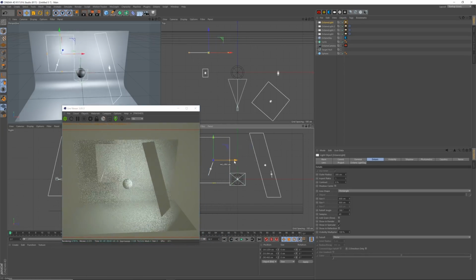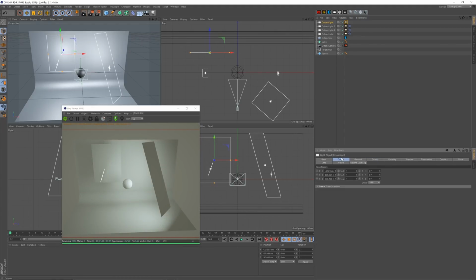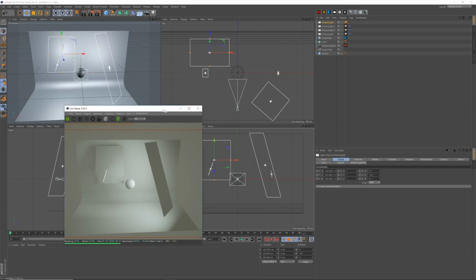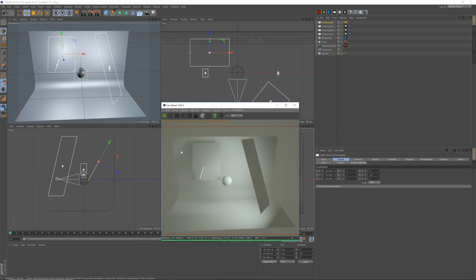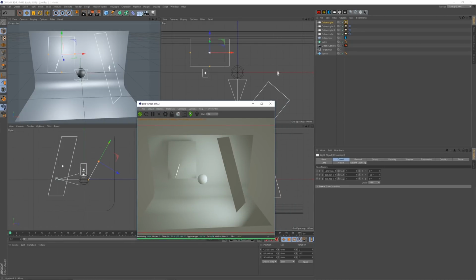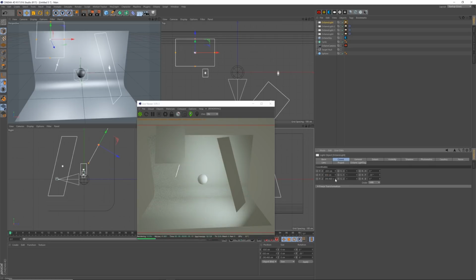This light is going to be off to the side. So let me go to coordinates, plug in -30, puts it on a bit of an angle, and let's put the coordinates at -650 and 650, and the Z at 300.